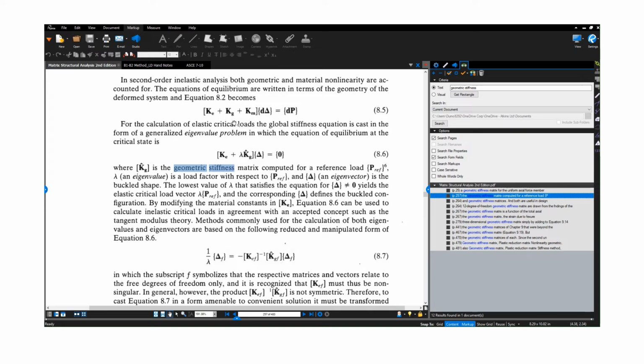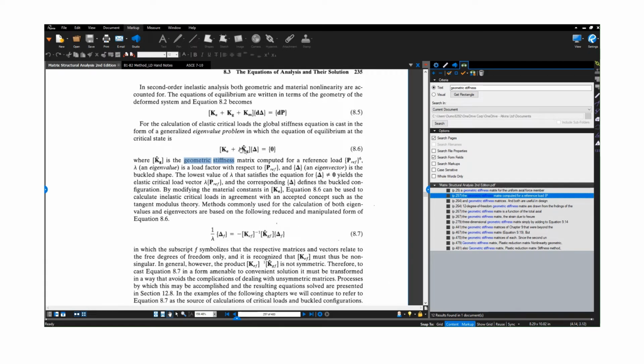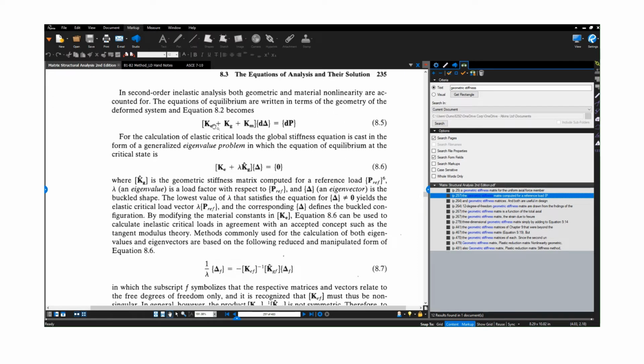for lateral load cases. Okay, so this is an example, even though this is not exactly what RAM is doing, but this is an example of combining stiffness matrix. You could just ignore the case of M right now because it's an elastic analysis, and M is dealing with plastic or inelastic behavior. So case of E and case of G is added together, and that is multiplied by delta to end up with a force matrix, internal forces, so external force matrix.